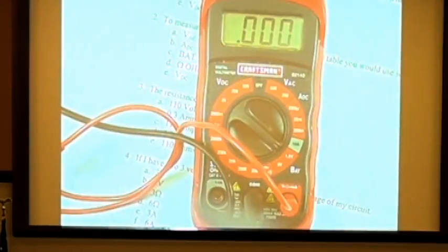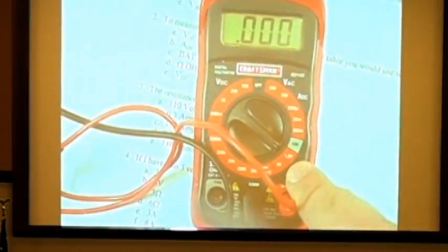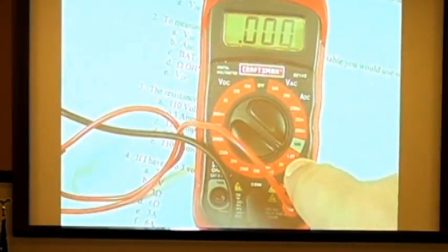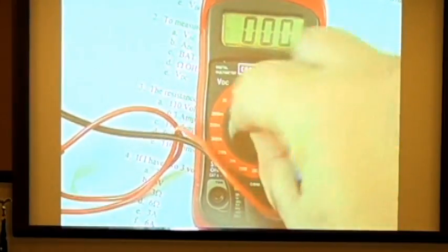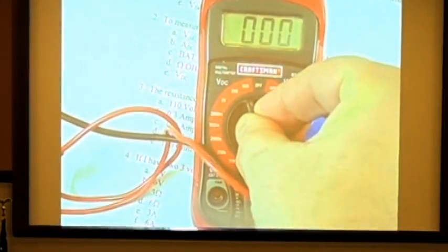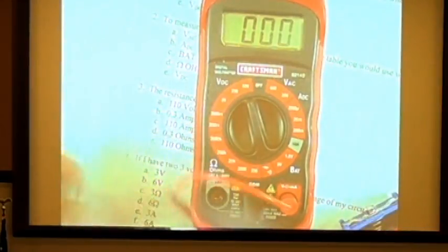The voltage on this battery, I'm giving you an answer. It's printed if you want to look at it, 1.5 volts, okay? Almost all D-cell batteries, they'll be a little bit higher if you measure them, 165, 180, somewhere around there. They're a little bit more, but they're generically considered 1.5 volts. So if you're going to measure something on this battery, it would be real good to use this scale that matches up here that says 1.5. You're going to get the highest accuracy than you would if you were to use something at this scale here, which would give you very low accuracy.